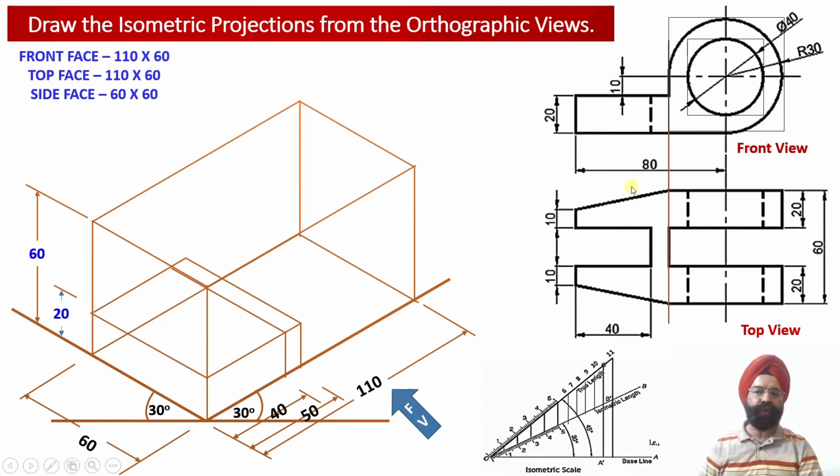This width is also 20 millimeter, and this rectangular slot width is also equal to 20 millimeter. So now we know that we have both of these webs located symmetrically around the center of the solid alongside the width of the solid. So the total width of the solid happens to be 60 millimeter. So we'll find out the midpoint. From the midpoint, we'll take an offset of 10 millimeter towards the left side, 10 millimeter towards the right side,